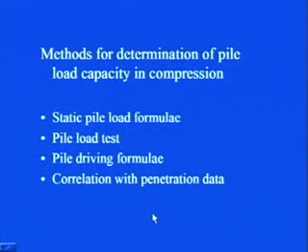Depending on what exactly the type of the soil is and what the method of installing the pile is, these empirical relations which have been developed differ from one to another. It is not necessary that a particular expression which gives you a very reasonable value at one particular site will give you an equally reasonable and good value at another site. It is not necessary. So, you have to judge which one you should use as far as the load capacity of the pile is concerned.